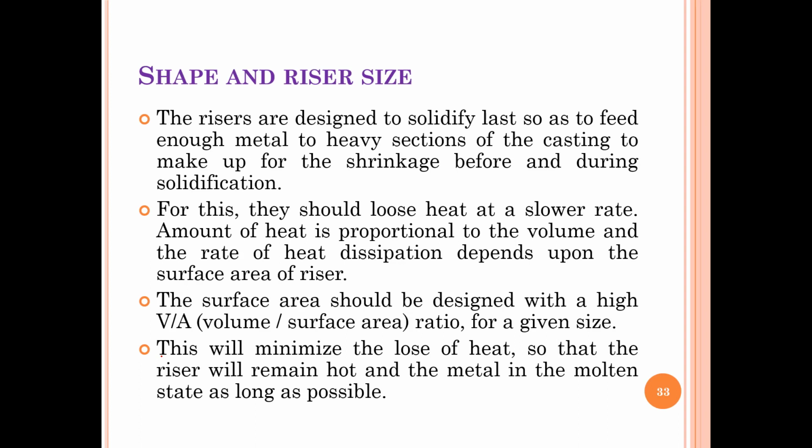Shape and riser size. The risers are designed to solidify last so as to feed enough metal to the heavy section of the casting to make up for the shrinkage before and during solidification. For this, they should lose heat at a slower rate.